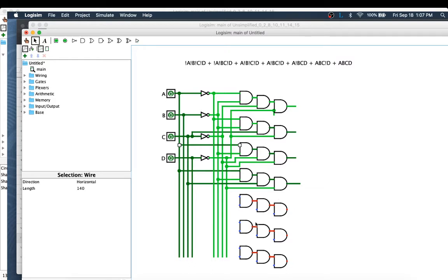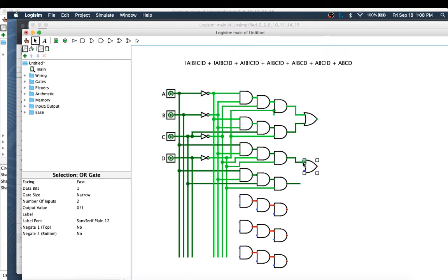So we're going to hook up all of these the same way. And I'm going to just show you how we're going to do. We're going to take each of these and run them into OR gates. And it doesn't matter which order you put them into OR gates. I could do the top two first, I could do the middle two first, it doesn't matter, because the OR operation is commutative. So I can reverse the order without changing the output. So I can do it like this, and then I could OR these two together. And as long as I end up having all these outputs from all these gates ORed together, when I'm done, I should have a good value.